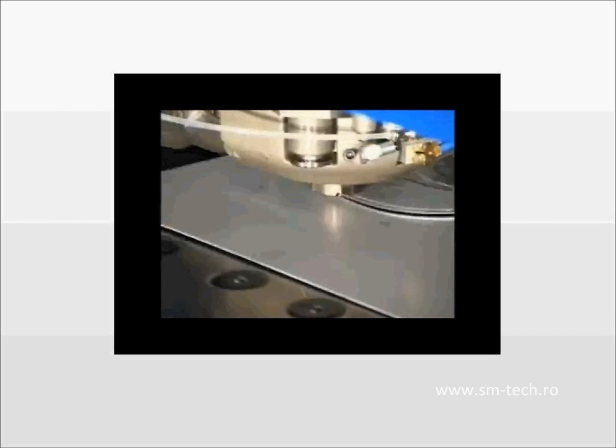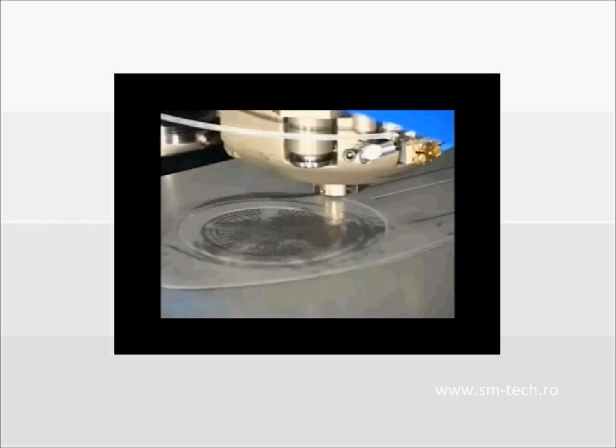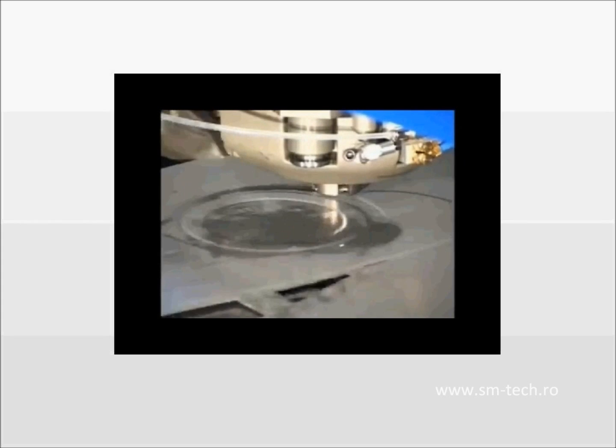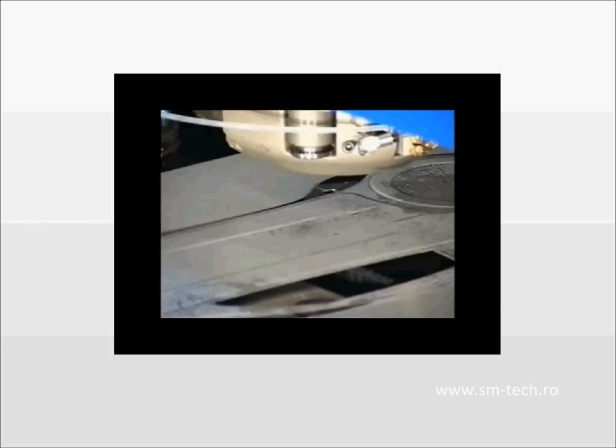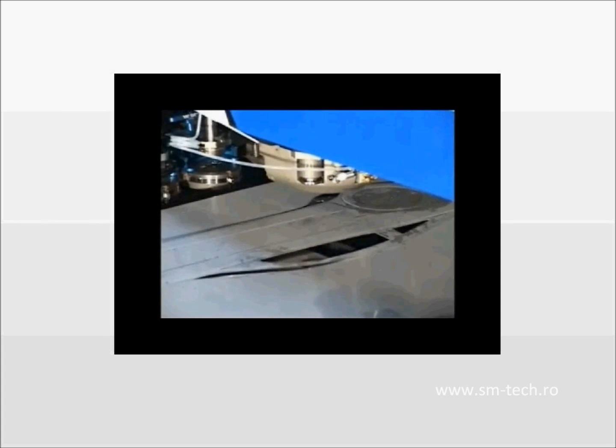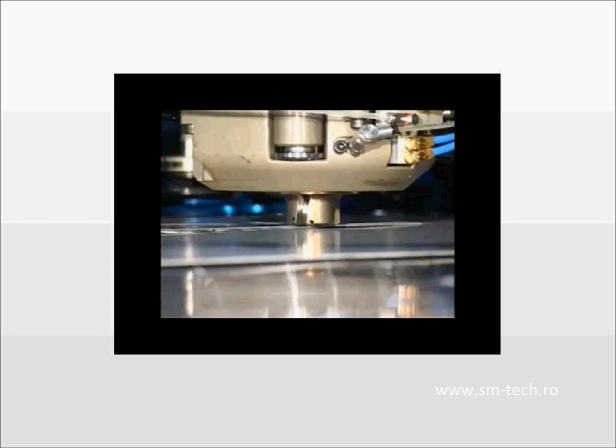So the machine brings the tool down and rolls, and moves the sheet underneath the wheel and cuts. And again, that's 18 gauge or 1.2 millimeter mild steel. So that's the basic function of that rolling shear tool.